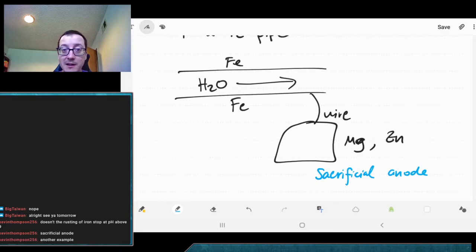So steel is a great material, right? It's very hard, it's very durable, it's a good material to use, very strong. So unfortunately, it does come with that risk of corrosion. So you'll either coat it, make stainless steel using various alloys, or you can use sacrificial anodes to protect your steel in this manner as well.